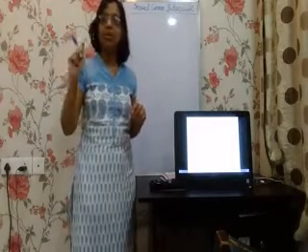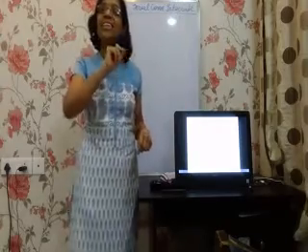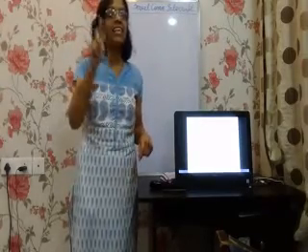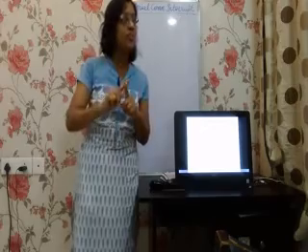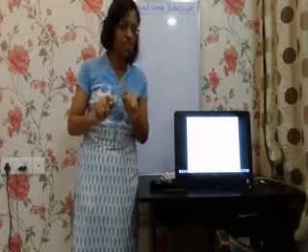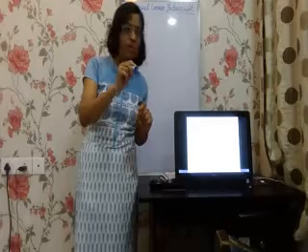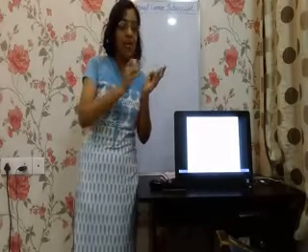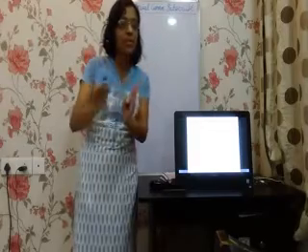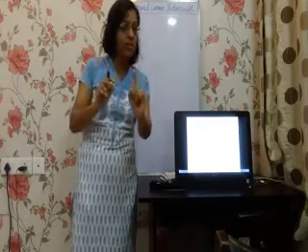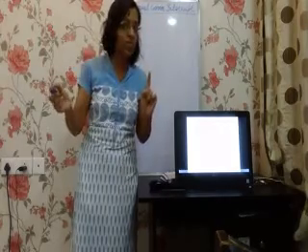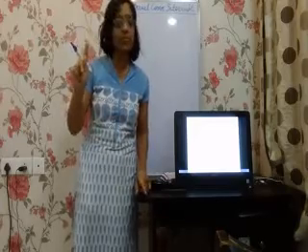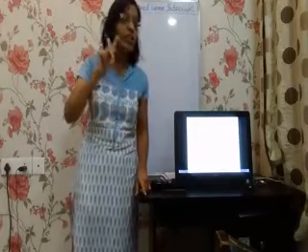The byte to be transmitted is loaded in the SBUF register, and then the byte starts getting transmitted bit by bit. Till the byte is transmitted, the TI flag remains 0. Once the complete byte is transmitted, the TI flag is made 1, indicating 1 byte is transmitted and the 8051 is ready for transmitting the next byte.